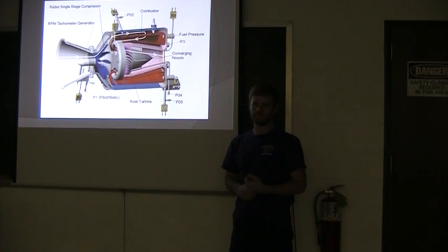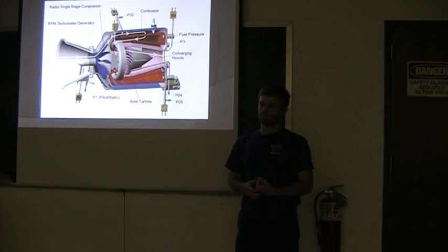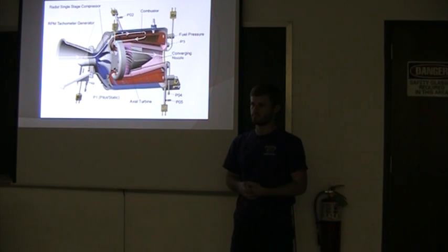Isn't the main purpose of the turbine just to run the compressor and compress it? Yeah, pretty much, yes. But then you are doing an expansion. The turbine is required for the expansion, right? Expansion of gas. So if you have to expand, without expanding the gas, you still have the high pressure. And then the high pressure goes directly into the nozzle.